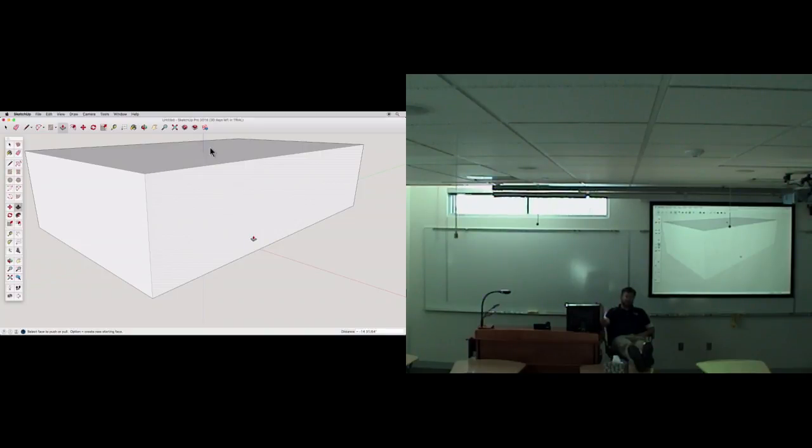But unless this model that you've created is a solid object, or what we call a closed surface drawing, the machine will not know how to do it. Okay, so what is a closed surface or a solid object? This box has surfaces that are defined on each side of the box, 6 surfaces that are all connected. There are no openings to the inside of the box. If there was an opening to the inside of the box, the machine that was going to try to carve it out of plastic would think that the box is hollow and would try to carve out a hollow box, which is very difficult for a machine to do if it's only got a small opening somewhere.